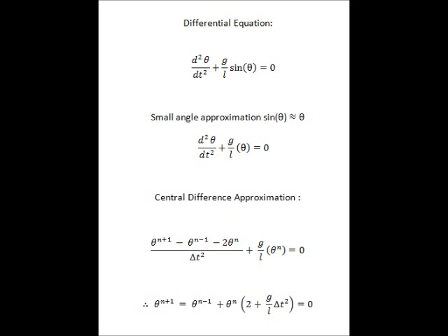The differential equation that can be used to describe the motion of a pendulum is the first equation shown, and that can be simplified down. Once it's simplified, you can use the central difference approximation to approximate theta, which is the angle, at future times.